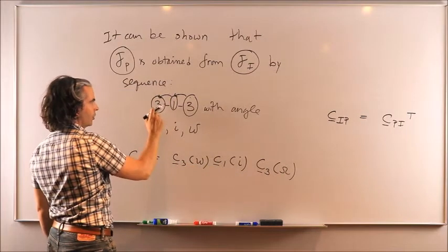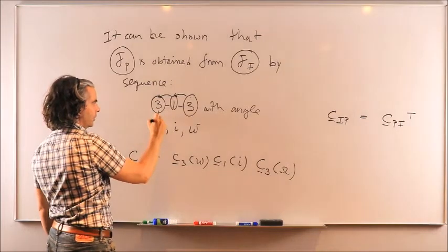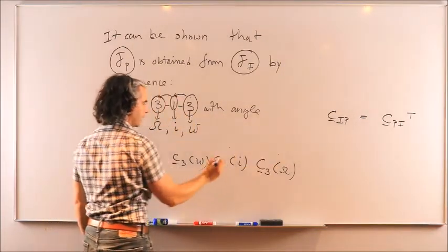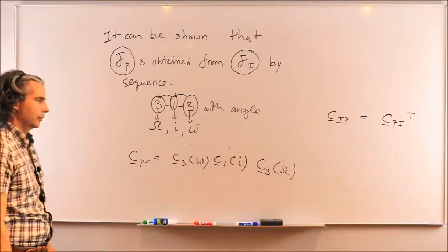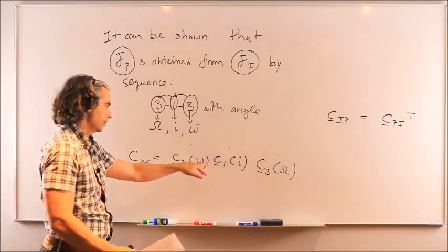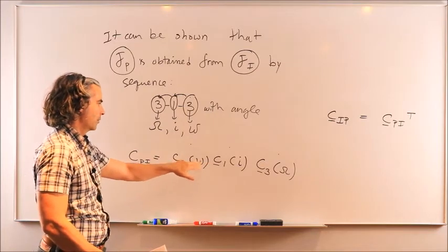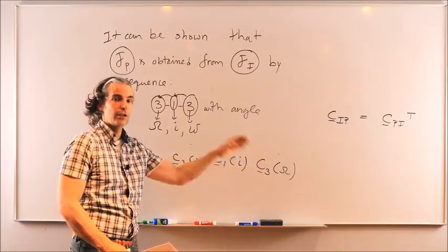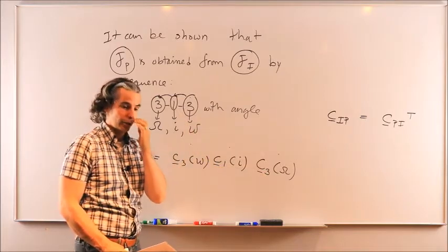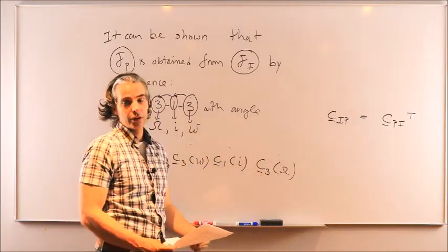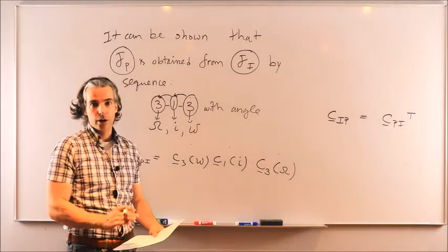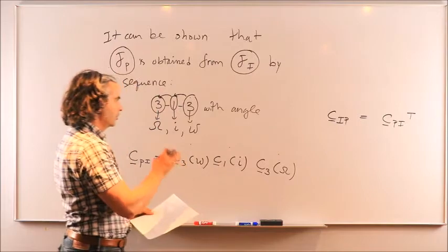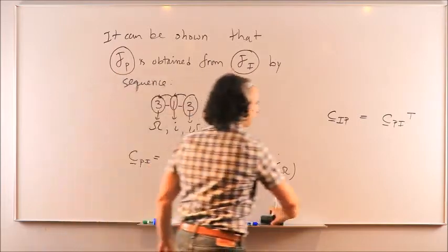And the order told me, or the sequence told me, that the first one was this, second, third, in that order. Don't mess up the order, so don't write C3 RAAN, C1 inclination, and C3 argument of perigee. You're gonna get the wrong result, and you're gonna lose 50% out of that question in an exam right away, right up from the get-go, okay? So pay attention to those details, they are fundamental.